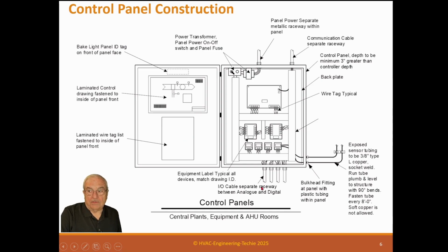So that's a general panel. It tells you how these conduits can come into the panel. Now, it doesn't matter to us whether they come into the top or the bottom normally, but the only thing that is important is don't mix cable types. Don't mix input sensors and output wires in the same conduit or the same area. You need to separate those just to be safe, so that there's never any chance of any RF signal coming in on an input. Output RF coming in on an output actually can come into a controller, but it's got to be pretty serious to do that.